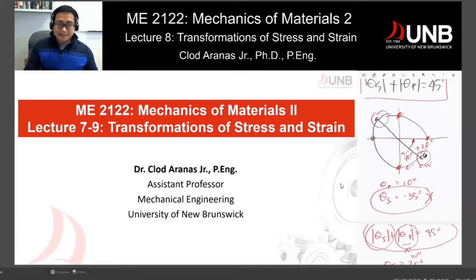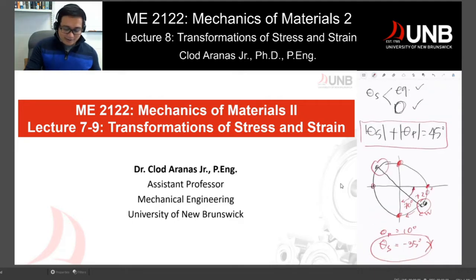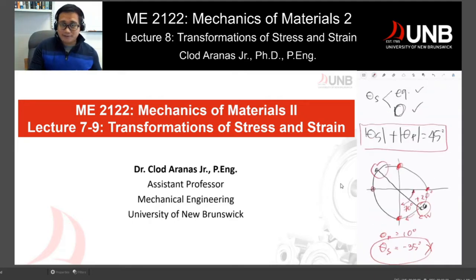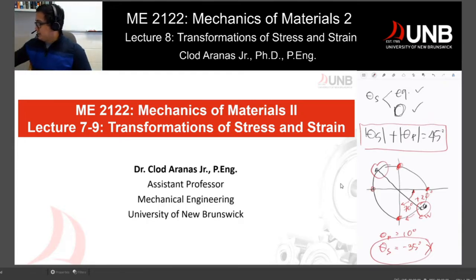But yeah, so that would answer that theta sub s question from last time, and that's really important if you are doing those calculations. So again, don't use this alone, this theta sub s plus theta sub b, to calculate your theta sub s. You may get the right answer, you may not. Just use transformation equation or Mohr circle. Of course, it's just either of the two if you have an exam or a question.